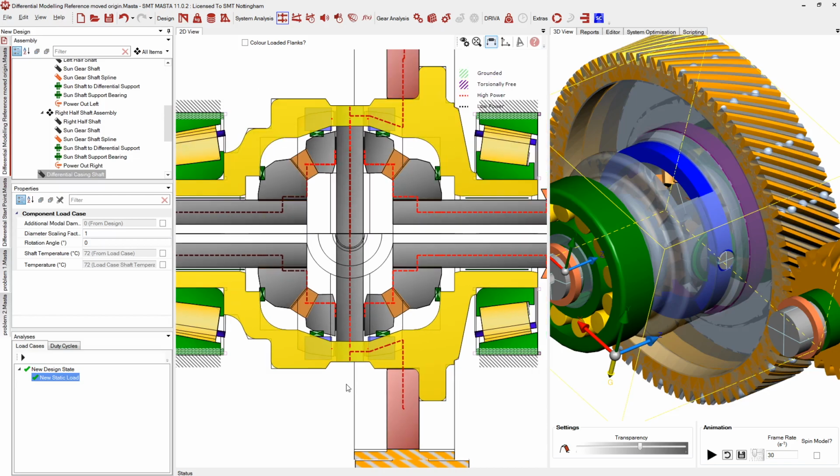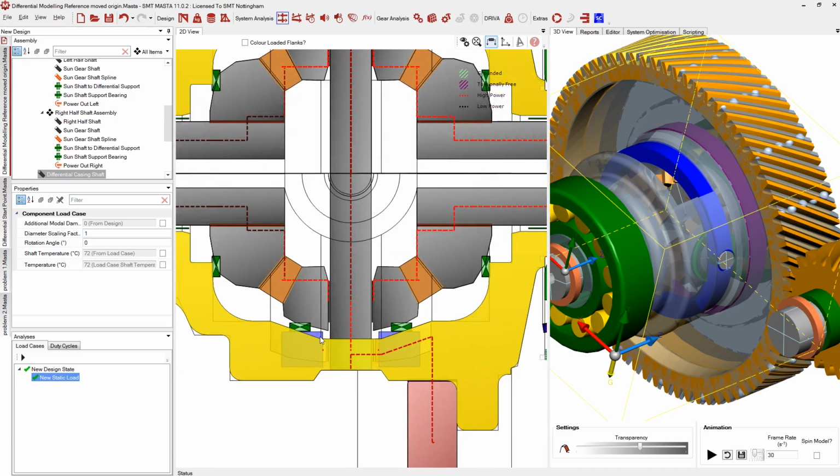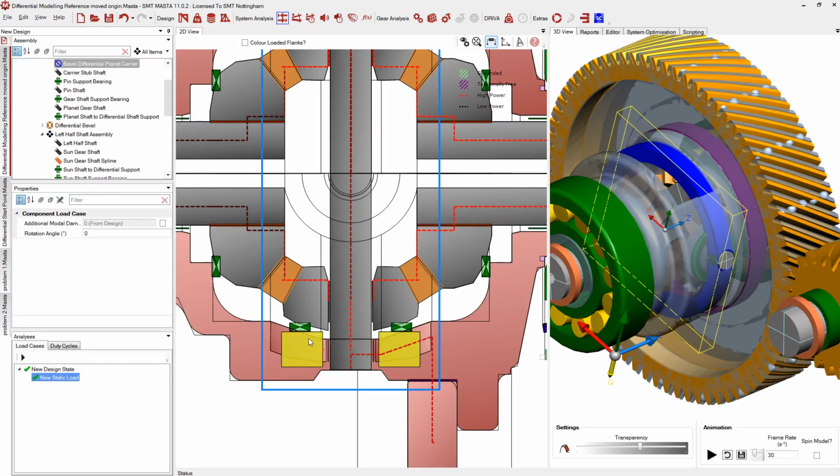So from our differential housing, where we're modeling in this direction, from left to right on my current screen, if we go through this blue component here, this differential carrier component, that switches the orientation of modeling. So the differential pin is actually being modeled from top to bottom on my current screen configuration. So this component changes that orientation.